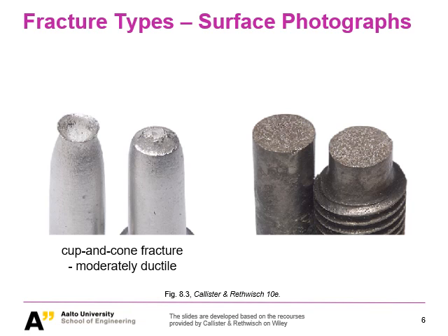And why it's ductile, you probably remember we also showed you some curves last time. If I can just draw here for you the engineering strain curve, I think everybody still remembers that. For the ductile fracture, we typically have the elasticity, yielding, the plasticity, and the fracture. So here we got our fracture. This is the ductile fracture.